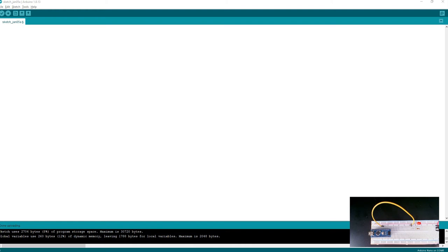There are other commands for reading variable types, so when you're interacting or asking a question, waiting for input, you could use a string for the serial monitor as well. There's a function called Serial.readString or readStringUntil, which we'll go into in another video, because right now there's plenty at this time. Let's go through a basic sketch.